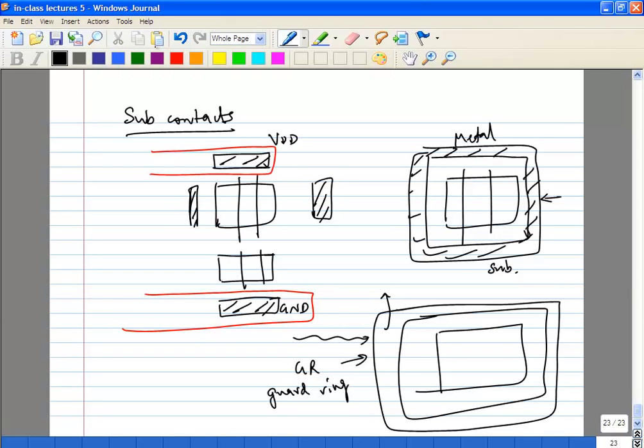Okay, and now obviously, let's say you have a guard ring and you have a substrate ring inside. Remember, because these two have totally different functions, do not connect them at the end to the same ground. Let's say this is your ground pad, use a separate ground pad for the substrate ring. If you end up connecting these two, it's almost the same thing as not having the guard ring. Because at the end of the day, it is going to go out like this through the low impedance path and come back to the substrate directly. You understand what I'm saying, right?